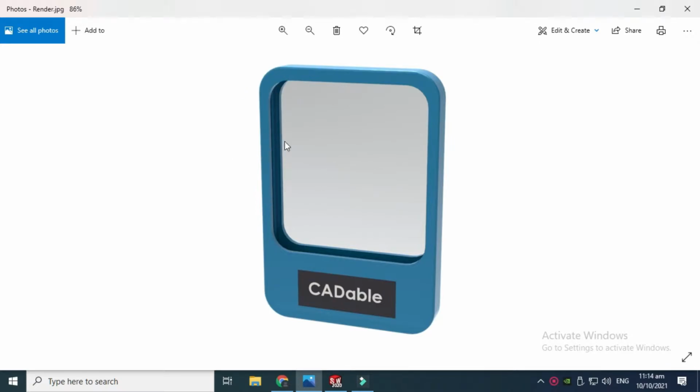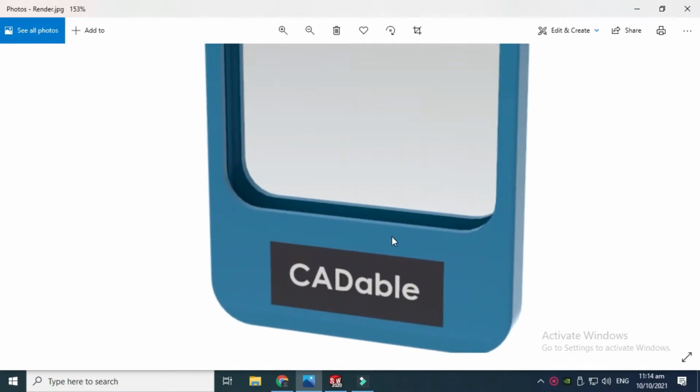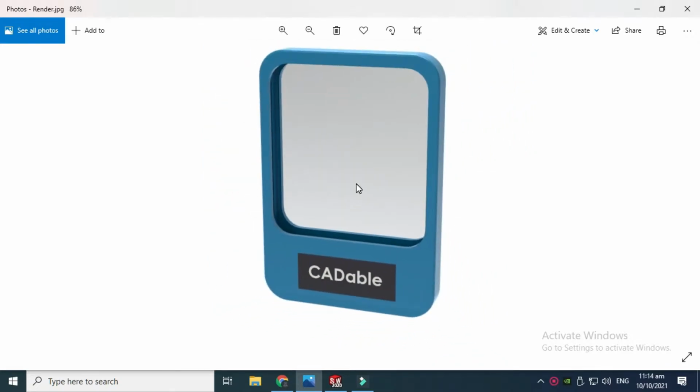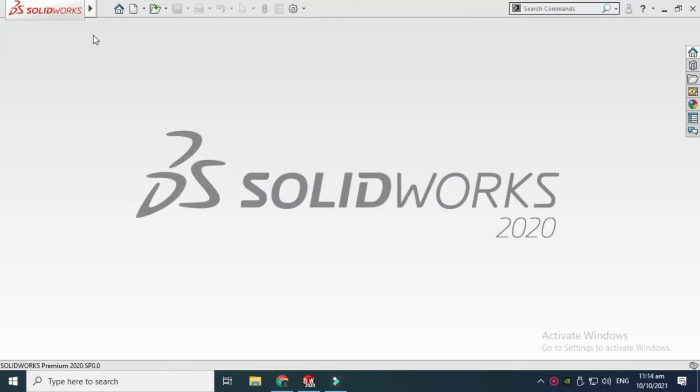Here we'll do some basic 3D modeling like Extrude Boss, Fillet, application of the shell feature, and application of text in Solidworks. Then we'll apply material in Solidworks to each part, and then we'll do some basic renders in PhotoView 360. Then I'll export this geometry to Keyshot 9, and we'll do some rendering there as well. So let's start.